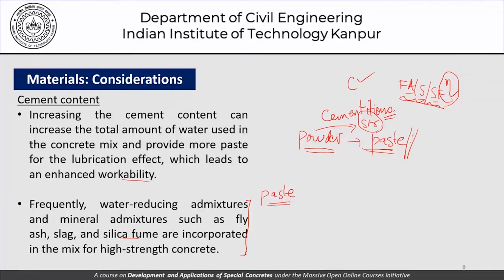We had talked extensively about the volume of water to volume of powder ratio kind of discussion. If these are the kind of properties which help us get fresh concrete right, and then we talk in terms of higher strength concrete, of course, what is the focus today is high strength, where we say that okay, we will use these mineral admixtures to the extent that we also get the advantage of higher strength.